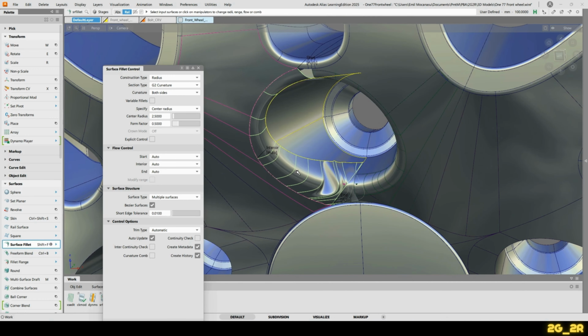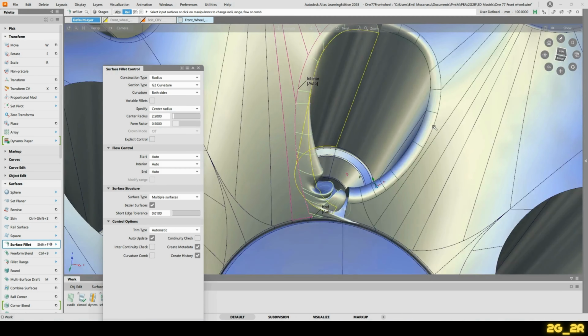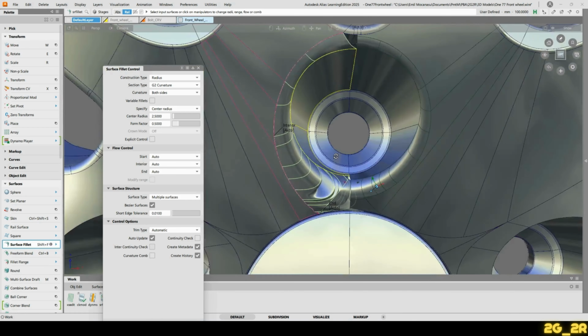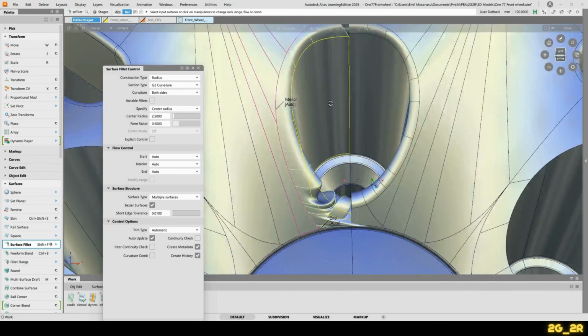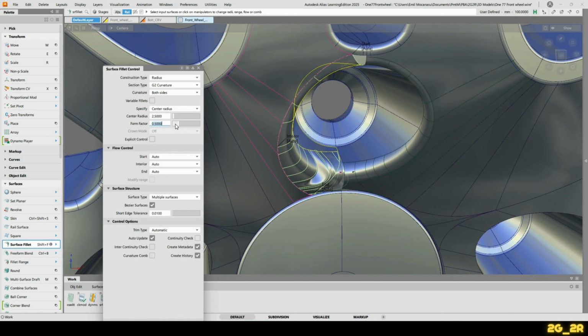G2 is what you use for main surfaces on automotive grade modeling. Here we could say we can stick with G1 because it's going from the face of it towards the inside of this technical bit here, so it could work. So what we need here to make it work, we can play around with the form factor, and let's see what that does.